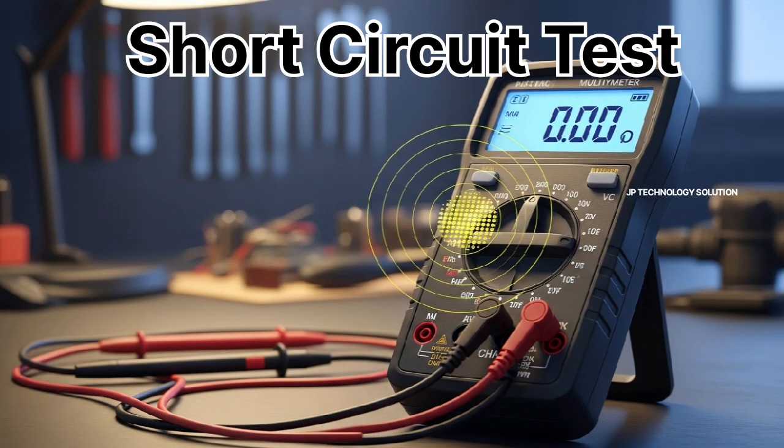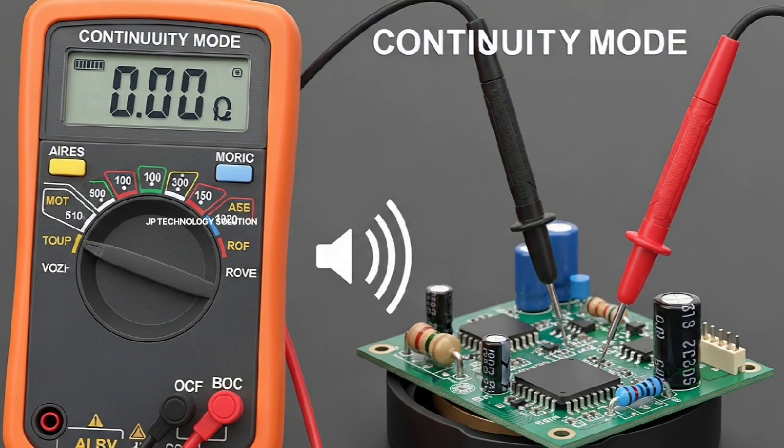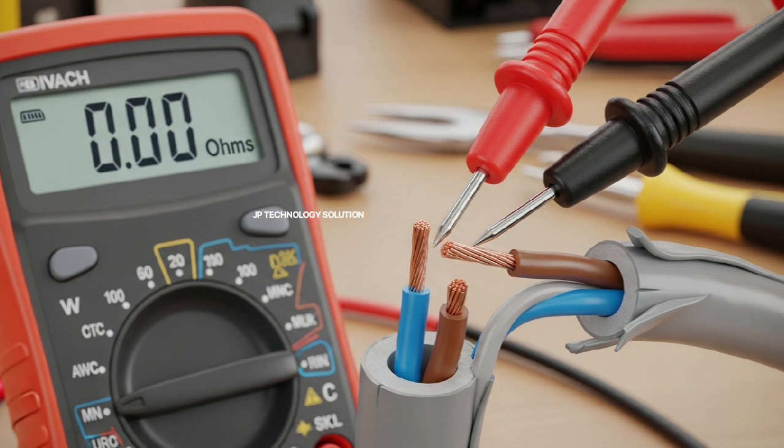Question 24. How to check for a short circuit with a multimeter? Set the multimeter to continuity mode or low resistance mode. Connect the probes to the 2 points of the circuit. If the meter shows nearly 0 ohms or gives a continuous beep, it means a short circuit is present. For example, if two wires inside a cable accidentally touch, the test will immediately show a short.